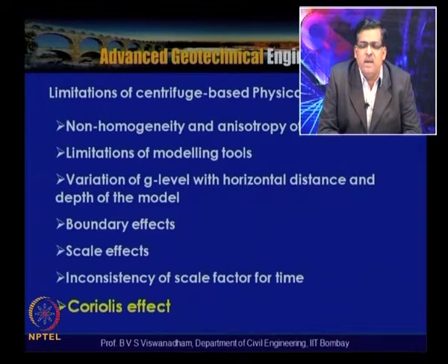So this needs to be eliminated by special techniques, particularly like applying white petroleum grease or a lubricating agent without affecting the transparency of the front view transparent glass wall, and by applying sheets in a special way, we can reduce this friction angle in a big way. So the boundary effects are important and need to be controlled, especially for sandy soil models.